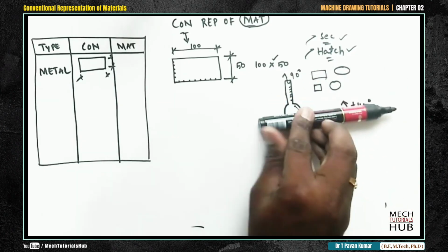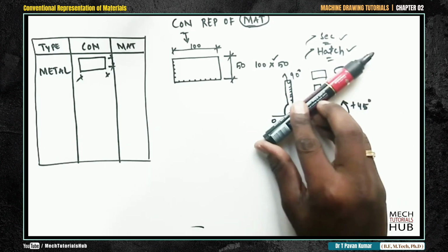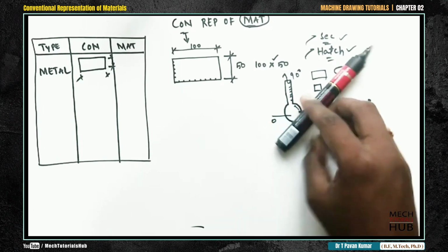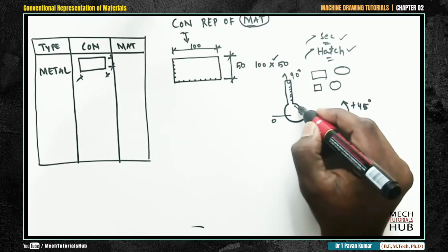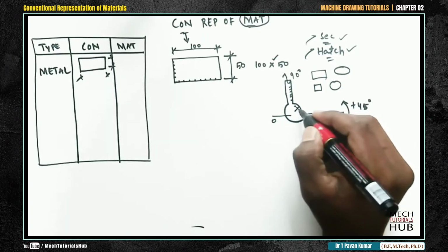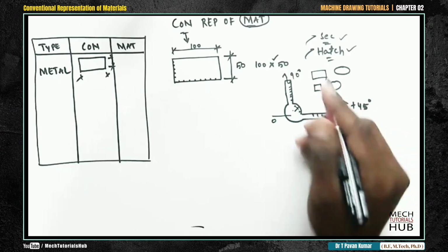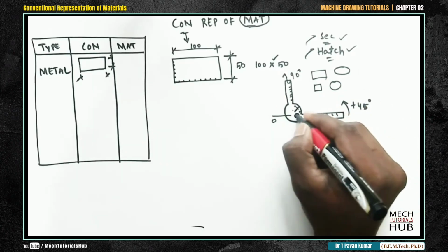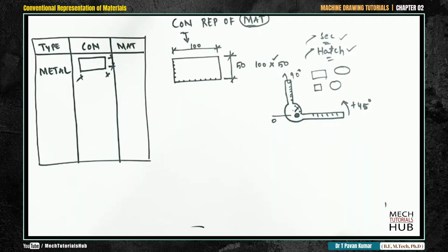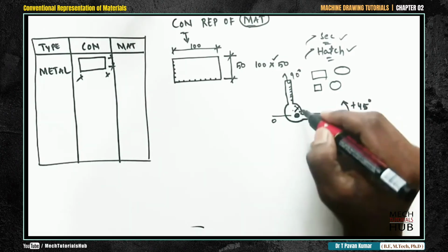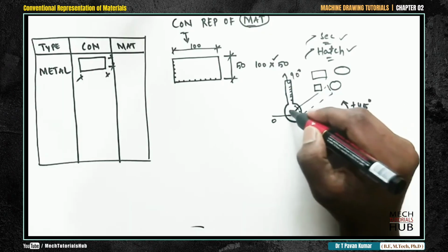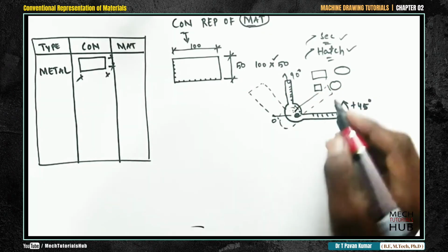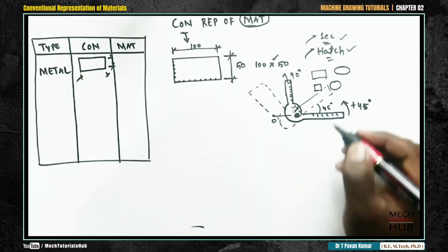Now for example, this is your scale. If you rotate to 45 degrees, just focus on the horizontal scale, not on the vertical scale. Where you could see a knob on your drafter, that will maintain that 45 degrees. Align your horizontal scale to that particular knob, then tighten the screw given on the drafter. Take that scale; your scale will be something like this after rotation. This is the position of your drafter after rotation to 45 degrees positive.